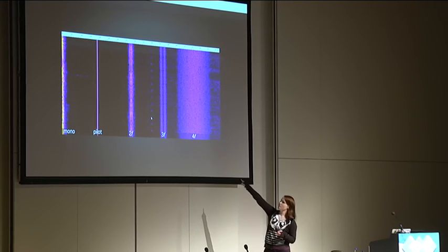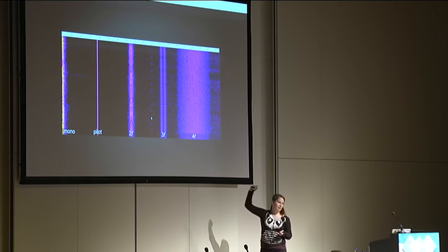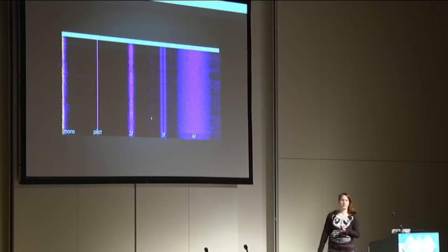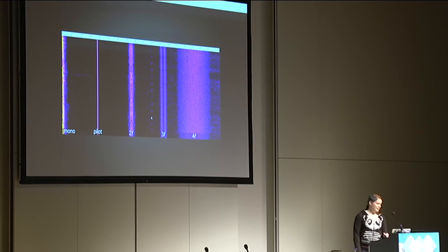And this fourth harmonic of the pilot zone contains obviously some data on a very wide bandwidth compared to the RDS. What could it be, and how could I ever find out? Well, it's centered around 76 kilohertz on the demodulated composite signal.